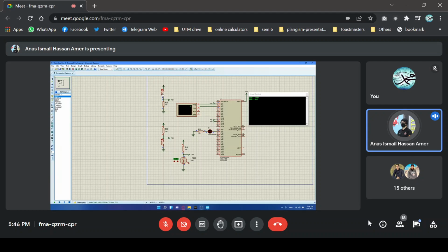So it's now 462. As I continue increasing, it should decrease even more, 253, and so on. 166. You can use this value then to do something inside the code, and you've successfully read the LDR value, or you have a way of sensing the LDR value.